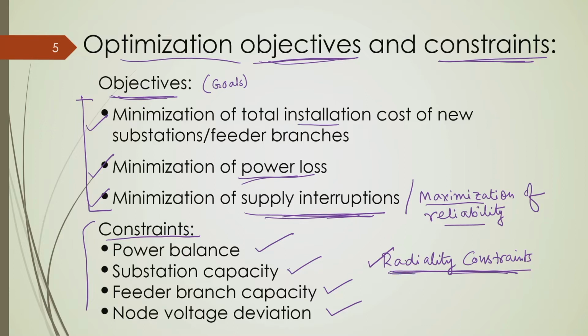As I have discussed many times, even though we have different distribution networks which might be weakly meshed or meshed, their operation is done keeping a radial network in mind. Even though a network is weakly meshed or meshed, its operation is radial, so far as passive distribution networks are concerned.